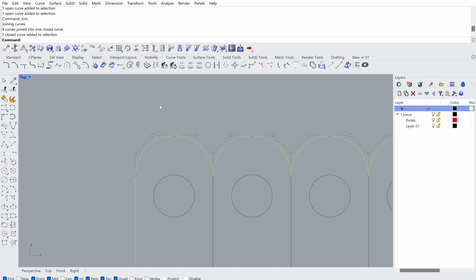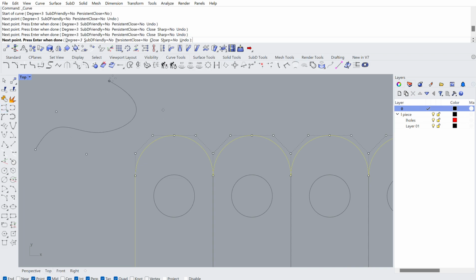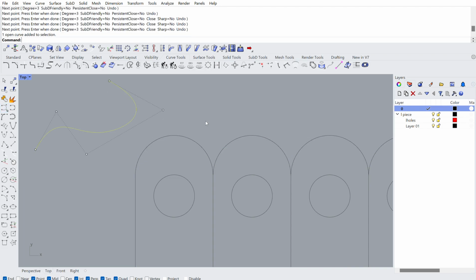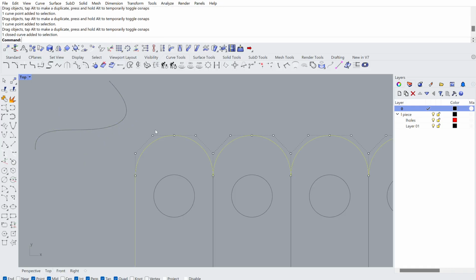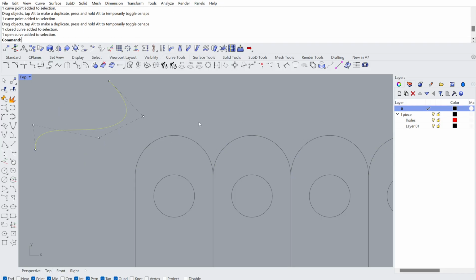So these points also, you might not always see those. Sometimes I forget what is the standard. Say I had some kind of spline. If you don't see the points and you want to see the points, if you're trying to edit your spline or edit your curve, you would do points off or points on.